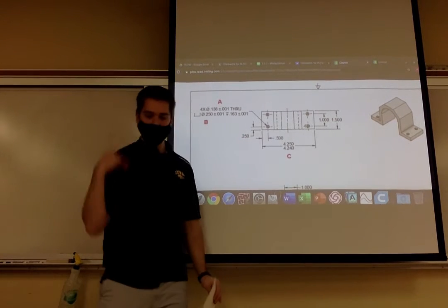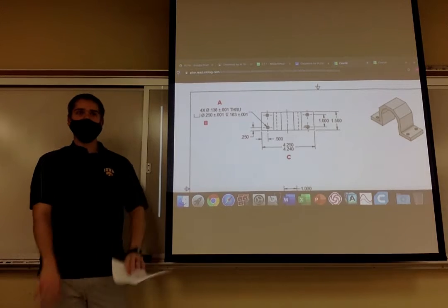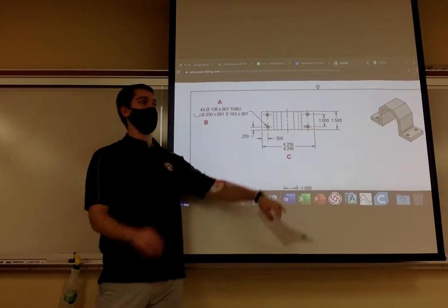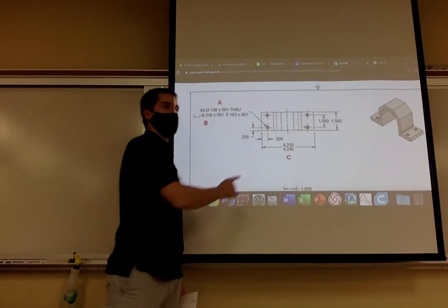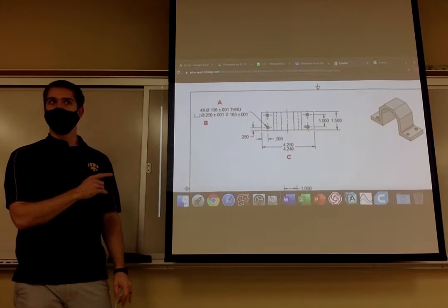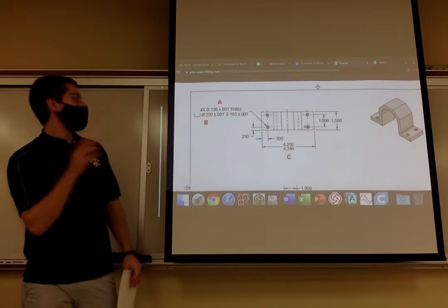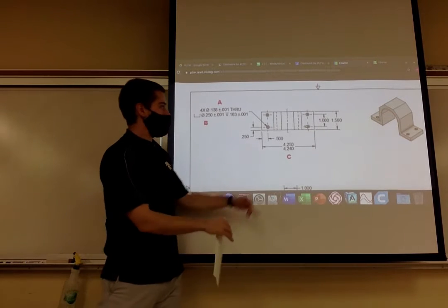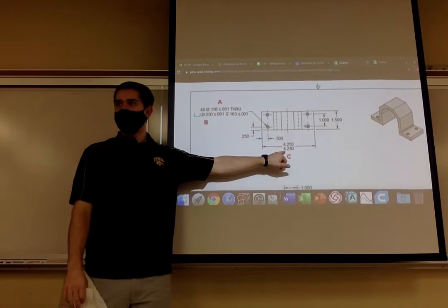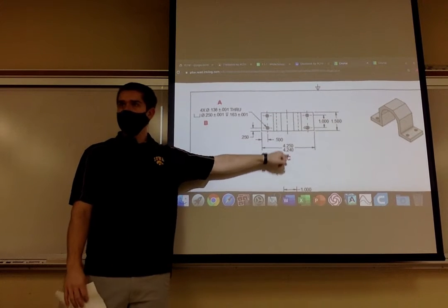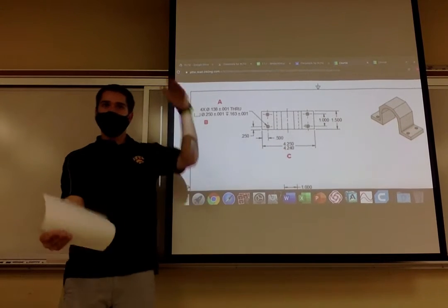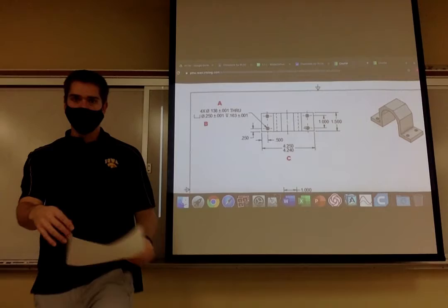Here's my upper limit. Here's my lower limit. Anything in there, I don't care. This literally tells you the limit. Now, what is the total tolerance of that dimension? 0.01. Correct. Anytime you want to take the upper limit minus the lower limit, well, it's already given. The range between the upper and lower limit is 0.01. So that is your total tolerance.